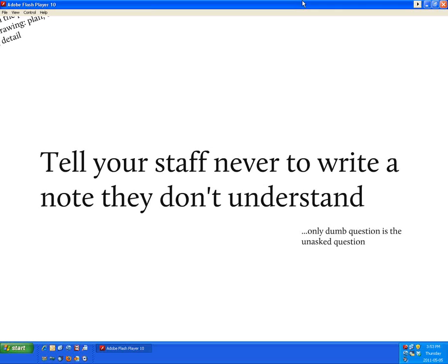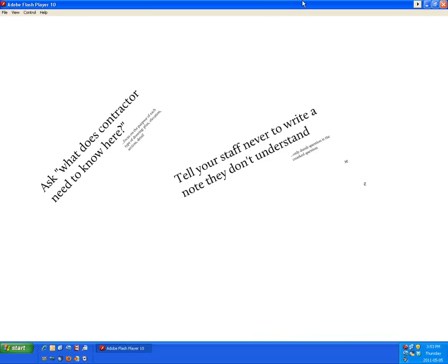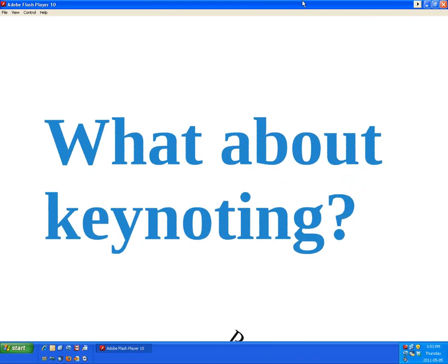I don't know how you could walk away from a note that you really don't know what it means. Oh well, I'm sure it happens. The brake metal example that I gave earlier, you'd be surprised how many people think that's a special alloy of metal. They don't know that it means brake-formed sheet metal, right? And that you have to identify what material.